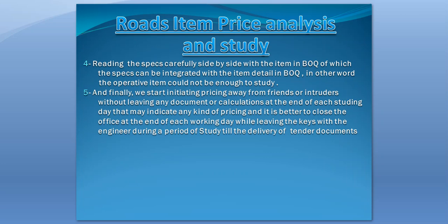For example, if you have an item like supply and install curb, in meter long, and you are not familiar with the specification, you will think that the curb will be constructed on sub-base or base, and the situation is over.